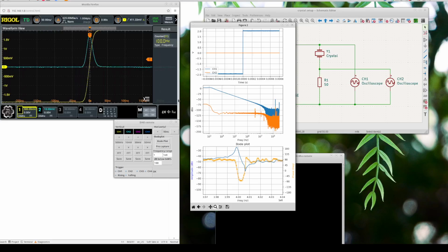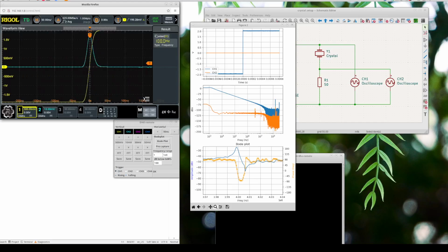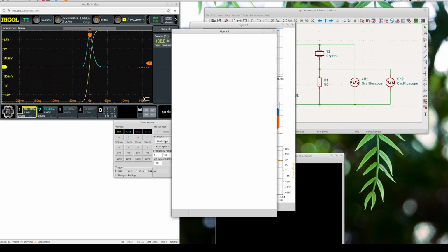Now one other tip is, the triggering is done on channel 1 if everything is correct. It's not entirely stable, as you can see. That's probably the quality of the scope. What I can still do is average out the signal. Once I do that, it becomes a lot less noisy. And that's interesting for making the next plot, so you can compare the noise.